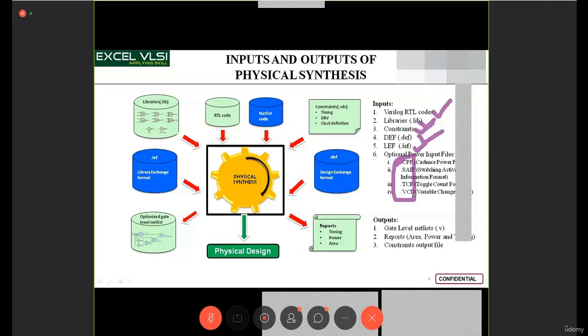That's what some of you are asking about, gated clock, clock gating. We also answered that we don't want the clock to be free running all the time. I want to provide the clock to a particular block only when that block needs it. So what I am trying to do is reduce the switching of that flip-flop.